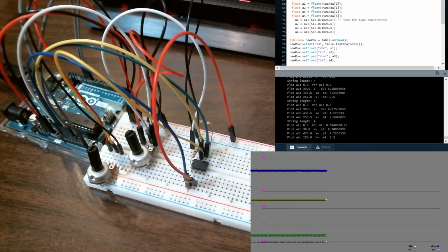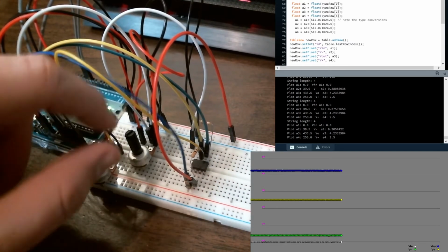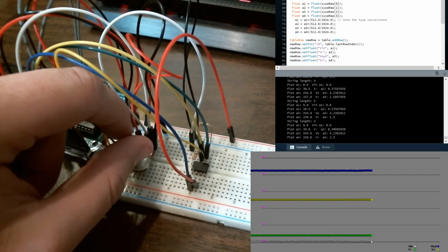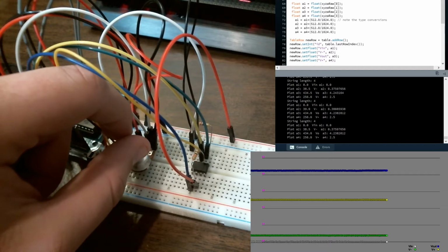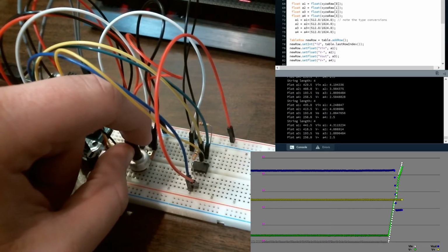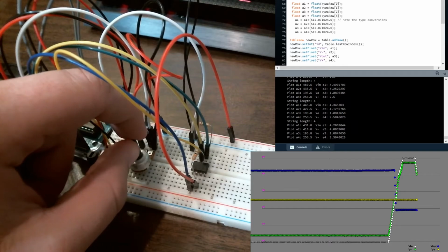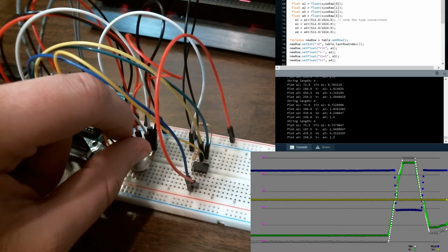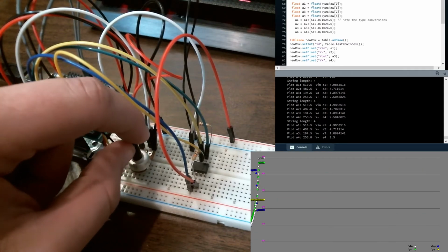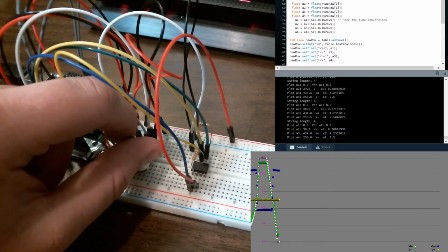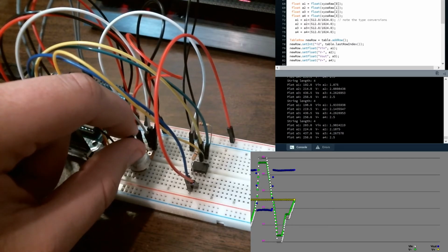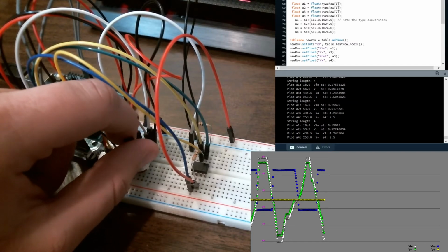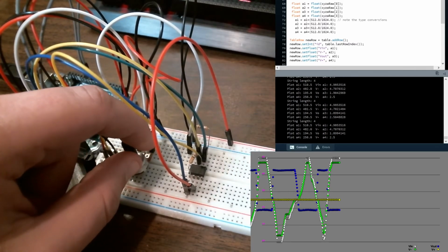Here's my inverting amplifier. I have the low input at 2.5 volts and the high input at 5 volts. Now I can move my V in from 0 to 5, and we have this inversion taking place. It's a little under 2 volts and a little over 4 volts where the plateaus occur with my output values. That seems to be what we should expect.